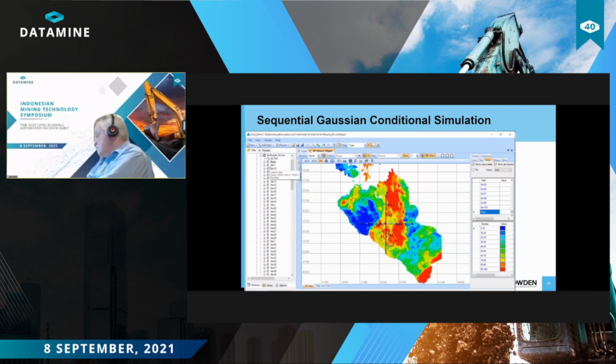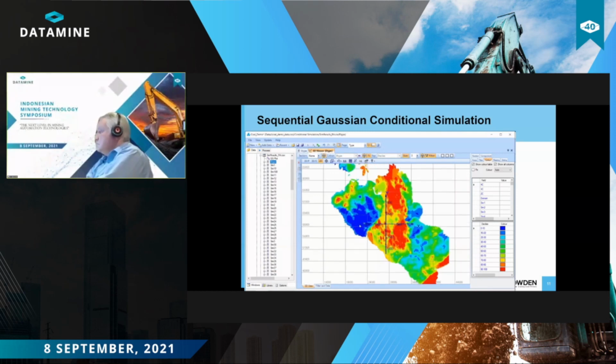If we remember that the E-type is the average of all the simulations, we can then go and look at individual simulations that ran. So this is simulation 1, and if we click through these, you'll see the picture changing, and you'll see the results of individual simulations that ran. All of the results of each of the 100 simulations have been averaged into the E-type here, which is our overall estimate.